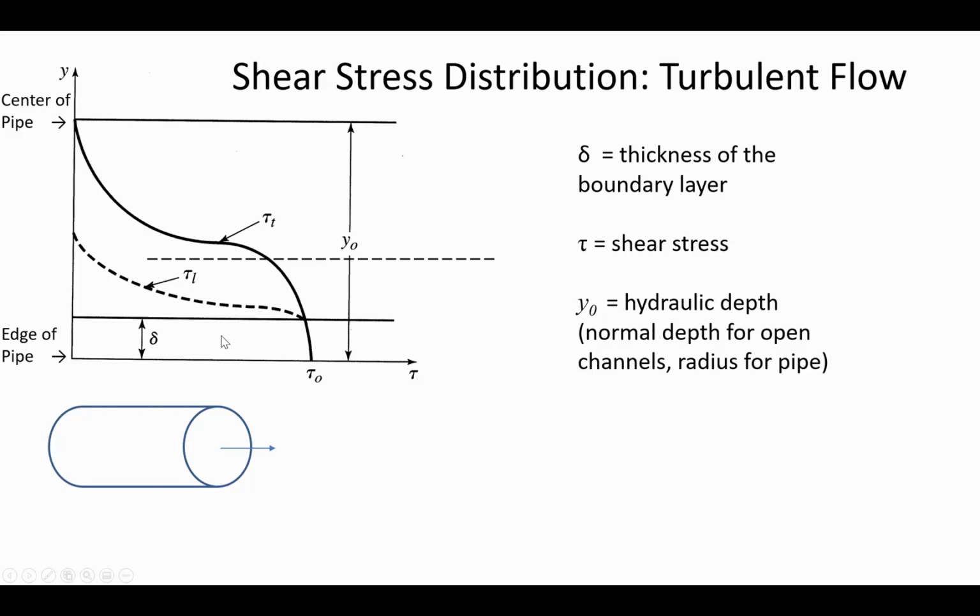The whole reason why we're looking at this is the idea of the boundary layer. A boundary layer is like a cushion. It's a cushion where the water is moving so slow that within that cushion the conditions are laminar. Even if in most of the pipe cross-section conditions are turbulent, there's this really slow-moving zone close to the edge of the pipe wall where the flow conditions are calm, quiescent, slow-moving, laminar, where there's just very little flow movement because it's so close to the pipe wall.